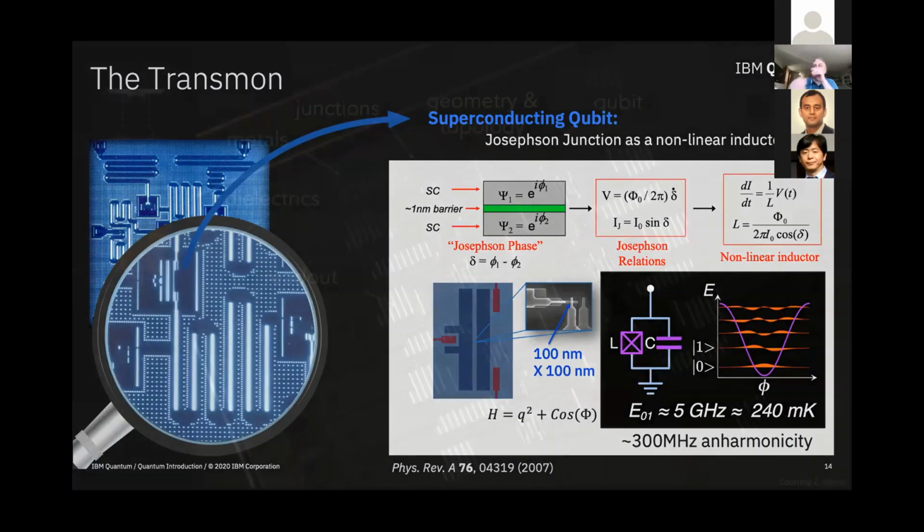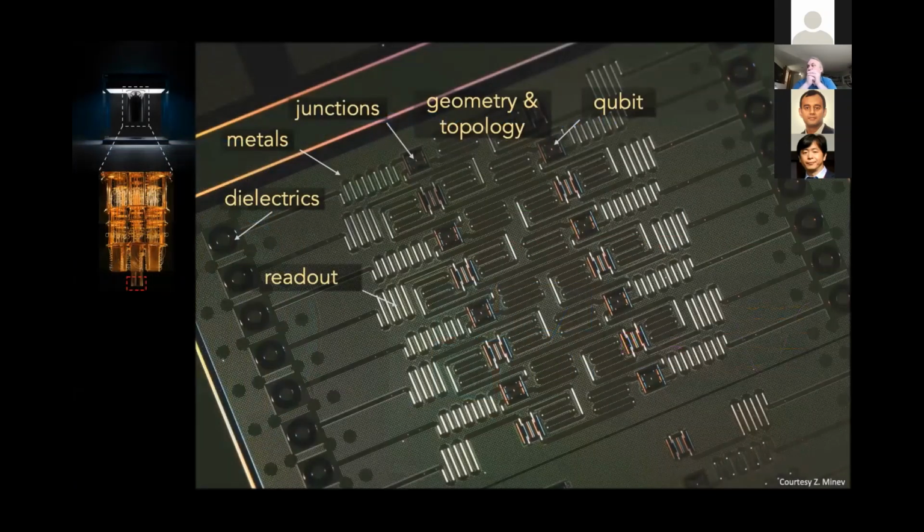And so here's sort of a picture of a relatively simple 16 qubit device made in this technology. You can see the qubits here. You see resonators providing that network that connects them all together so I can run my 2 qubit gates. You can see some additional resonators over here that connect the qubit to the outside world. And those play 2 roles. They protect the qubit from the outside world, but they also allow me to measure the state of the qubit because it turns out the frequency of that resonator will depend very, very slightly on the state of the qubit. So when I want to know the answer at the end, I can get the answer.